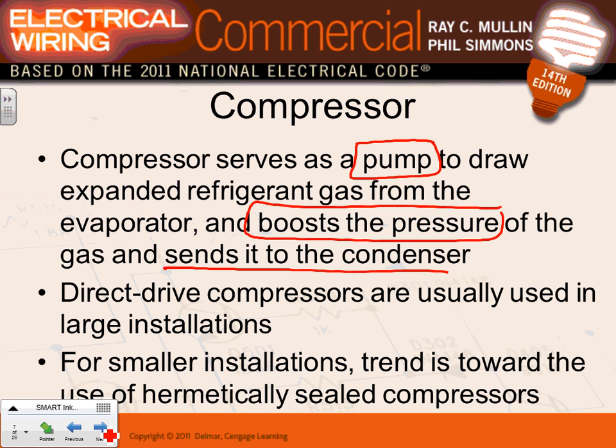It pumps it, increases the pressure, and shifts it back to the condenser. Now we have a reduced temperature, not completely reduced, but reduced, still has heat, and then you blow the air through that high pressure gas to remove the heat into Mother Nature, and change it into liquid, and keep doing the process over and over.